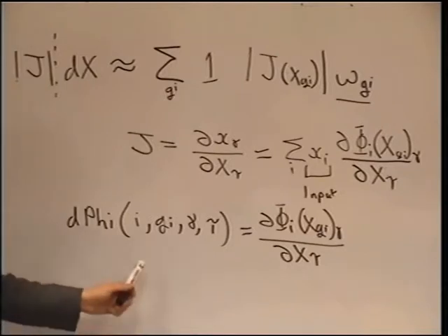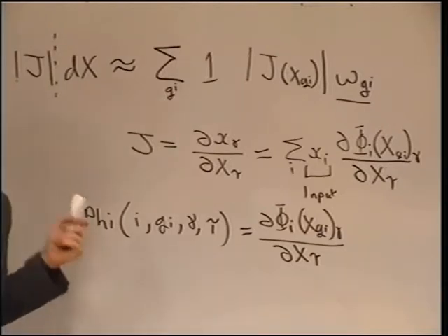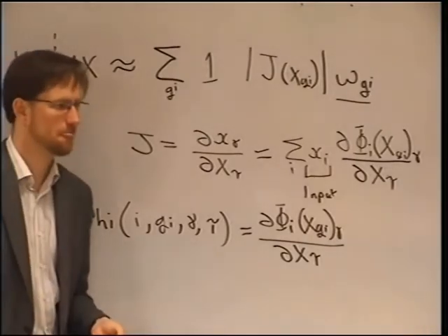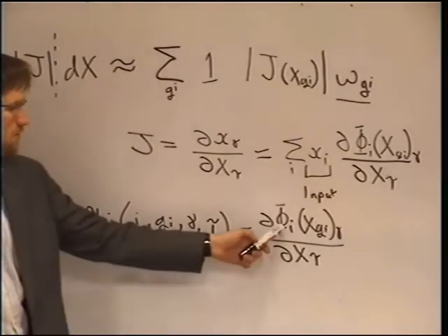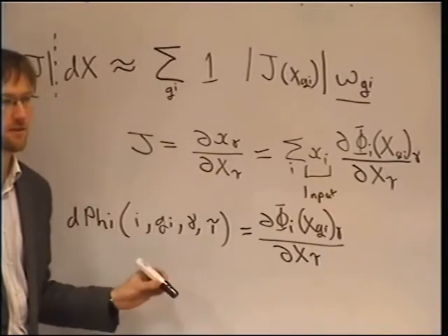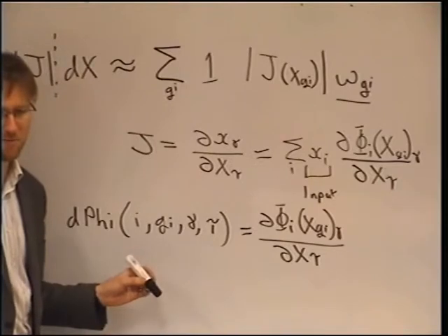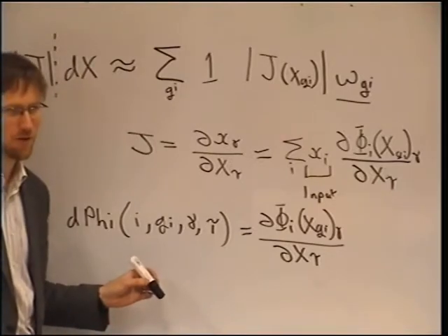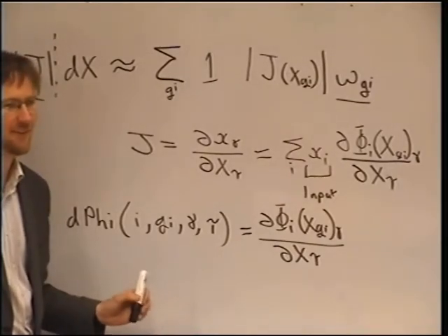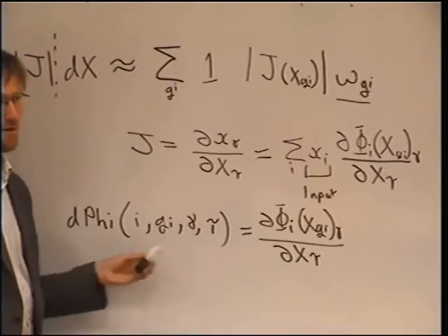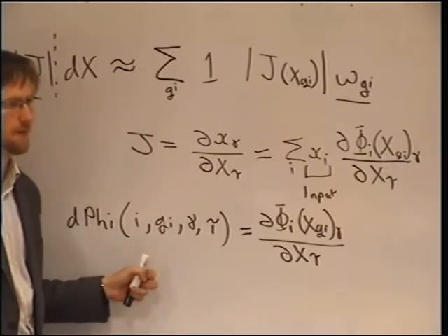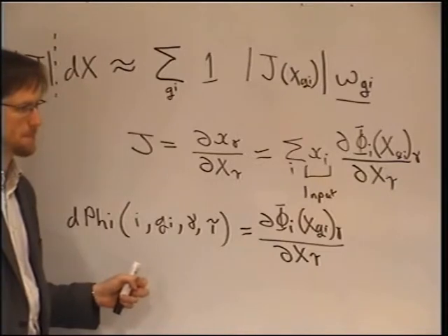For big elements, that's quite big. So for high order elements in more dimensions, that can be a lot of static data. For the people who are interested in tensor product elements, there are smarter things that you can do. You could factorize this and store the factors of this matrix. If you did that, you'd store an awful lot less static data. So when people from time to time hear me complain that our implementation of tensor product element is stupid, the sense in which it's stupid is that we don't factorize this. We really do currently write down that whole thing, and that gives you a huge amount of static data.